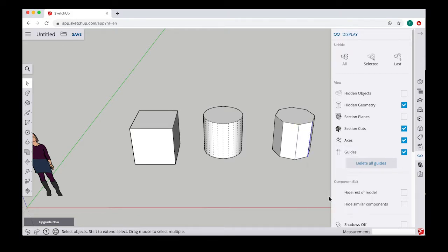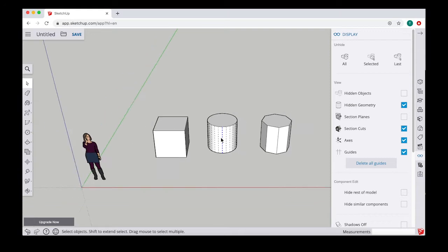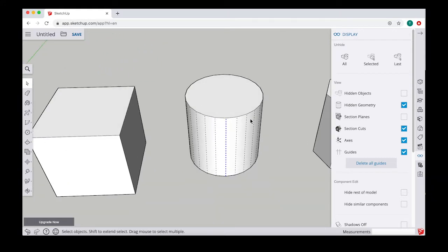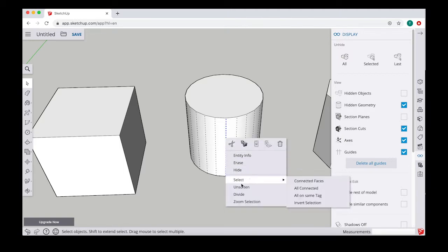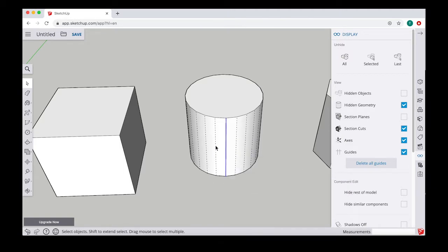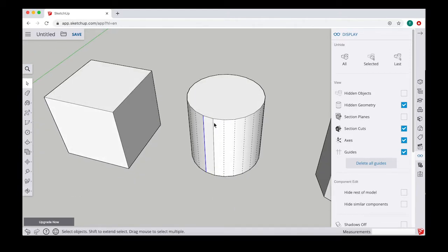And the inverse is true for the circle, so you can actually select these hidden lines here, because in reality this circle is just a collection of many different lines. It's just a polygon with loads of sides, because Sketchup can't do fully smooth curves exactly, just a selection of lines. So you can unsoften these and you can create a hard edge with this. So this will be a straight line. These will be straight lines, and you can play around with that, and then again you can soften those again by right clicking and soften.